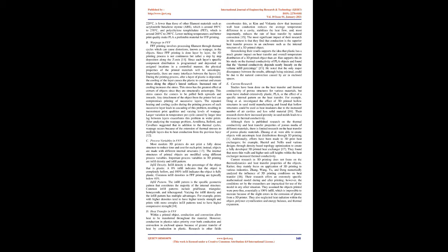Warpage in FFF. FFF printing involves processing filament through thermal cycles which can cause distortions, known as warpage, in the objects. Since FFF printing is done layer by layer, the 3D printing process is not continuous but rather a step-by-step deposition along the z-axis. Since each layer's specific component distribution is programmed and deposited on assigned locations in a controlled manner, the physical properties of the printed materials will be anisotropic. Importantly, there are many interfaces between the layers.